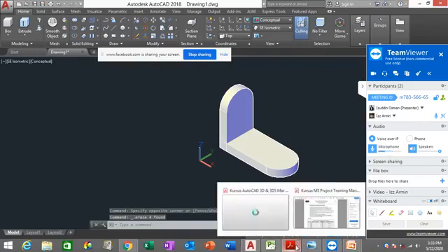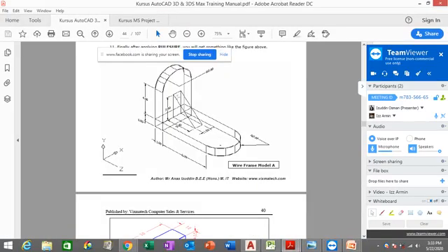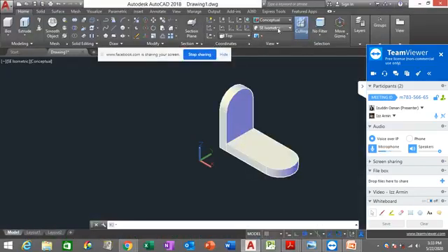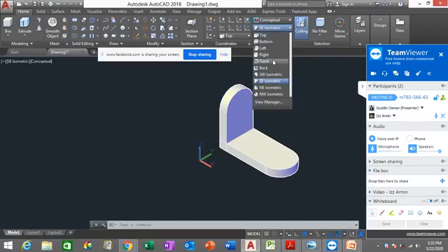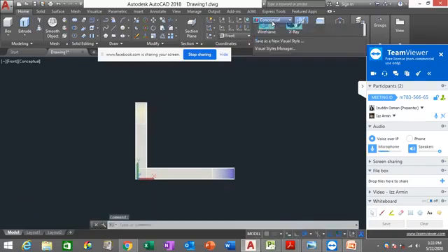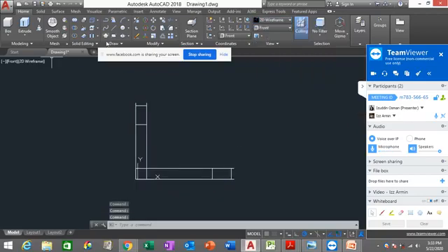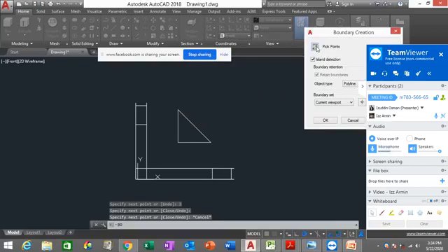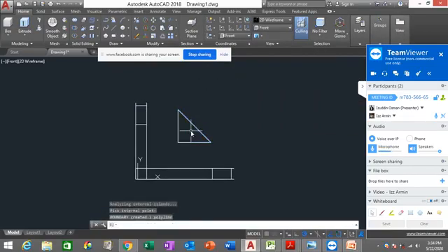So now you are going to create this triangle on the middle section here. So you're going to change your view first to front. Alright, to front view, like this. Okay. And you're going to open up this, change to 2D wireframe. You click line, click here, polar track this, 3, enter. All right. And boundary. BO enter. Pick point, click inside this triangle, enter,